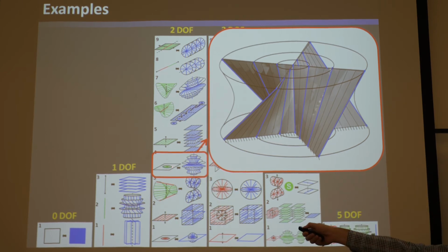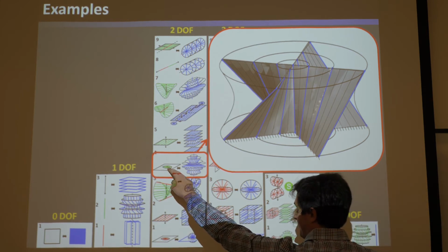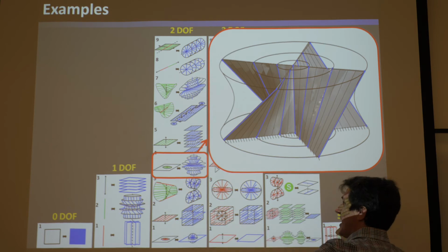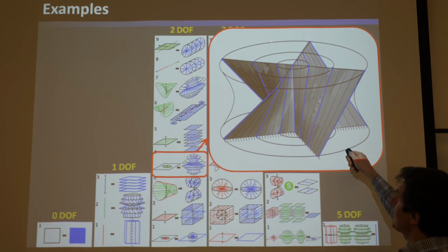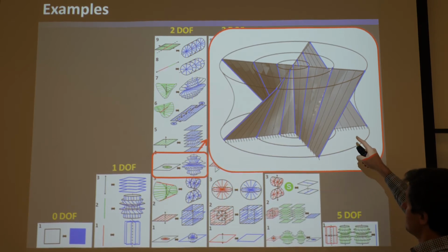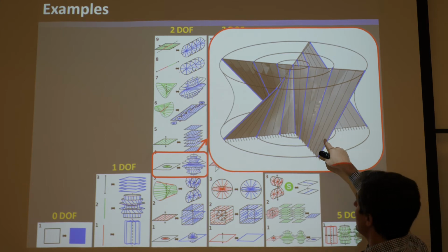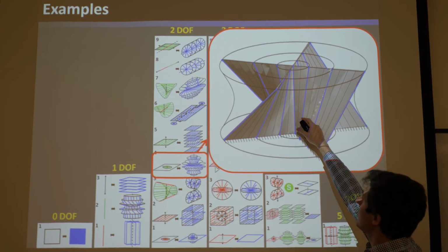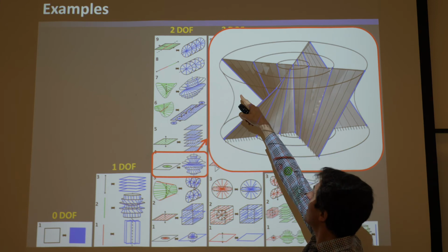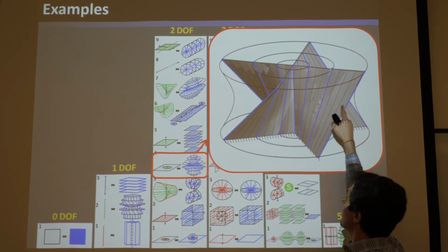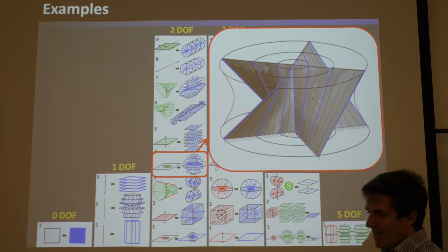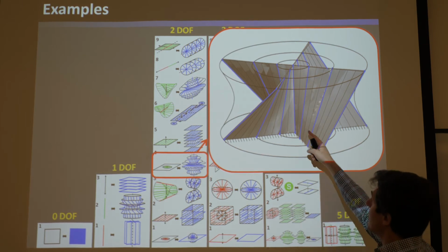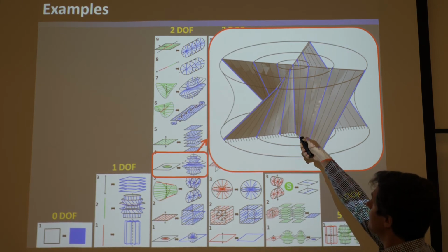If you want to achieve your disk of screws with the same pitch, which is what that freedom space is, then you could get a parallel element from within this geometry. And you can see this is basically a hyperbolic paraboloid flexure, this one that goes through there. And this is another hyperbolic paraboloid flexure that would have, and they're fused together down this central line.